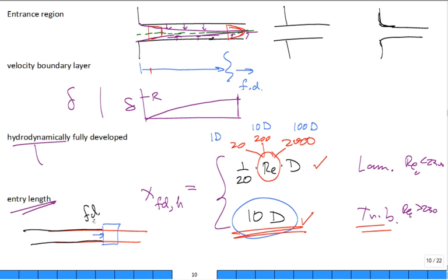They can't test, and they won't test, a 45-degree elbow 3 diameters before the flow meter, or a 90-degree, or a union or a T right here that brings in a flow and then turns it, and then move it closer, further away. There's too many things to test. They're all based on the assumption that you have a nice long straight run before you hit that flow meter, and now it's coming into it with a nice, uniformly developed, fully developed velocity profile.